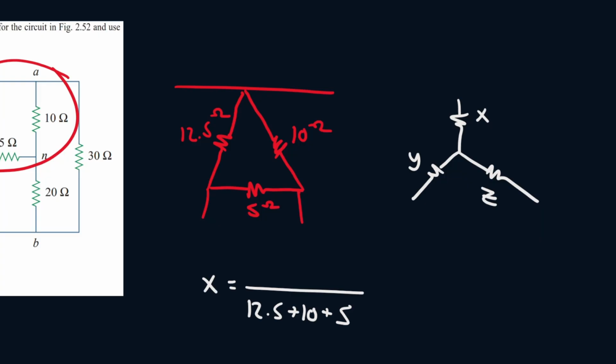So the first thing we're going to do is look down here. Look at the X and look at this portion. If we draw a dotted line straight down, aligned with the X, we notice we'll hit this 5 ohm resistor. So that means we won't include that 5 ohm resistor in the numerator. Now that means we can only include these two.